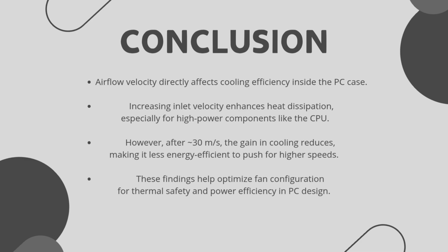However, after 30 meters per second, the gain in cooling reduces, making it less energy efficient to push for higher speeds. Therefore, when we increase the velocity too much, very little efficient cooling is being made.